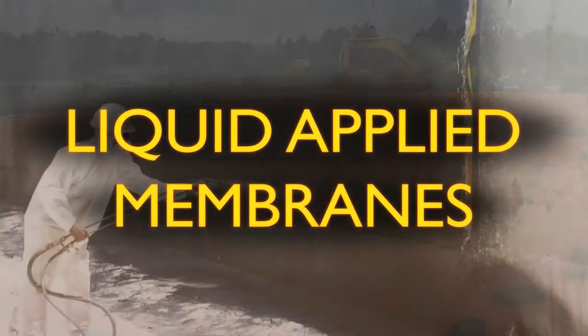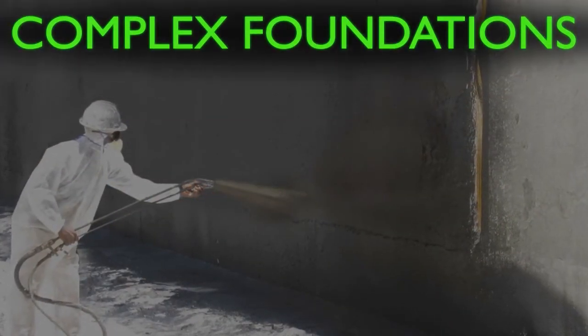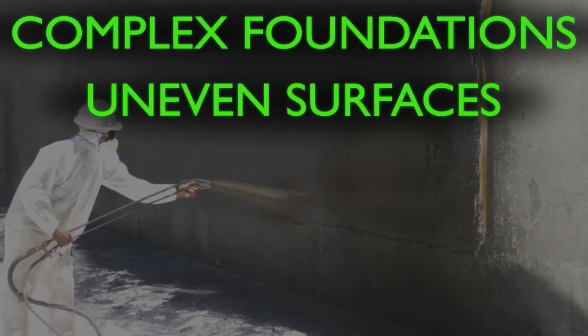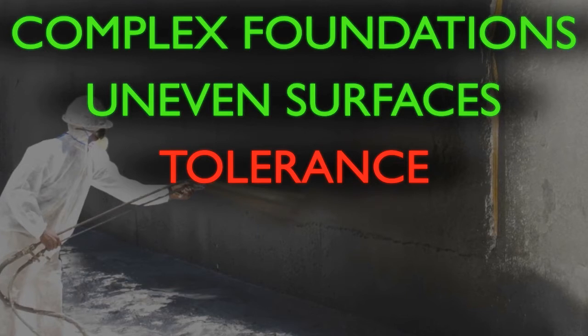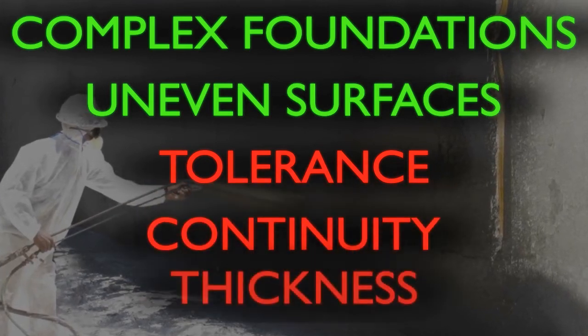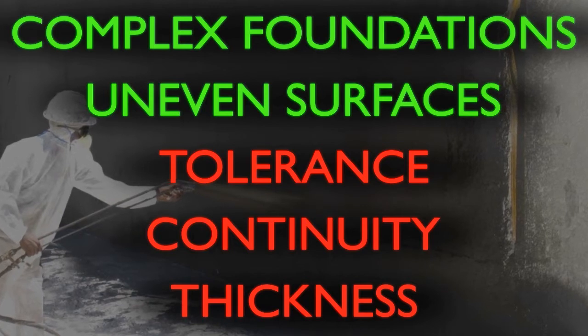Liquid applied membranes. Liquid applied membranes are ideal for complicated foundation detailing on uneven surfaces. The downside to these systems is it's not always easy to determine the tolerance of the application, such as the continuity or thickness of coating. Liquid applied systems do, however, make a good companion to sheet membranes where complex details must be sealed.